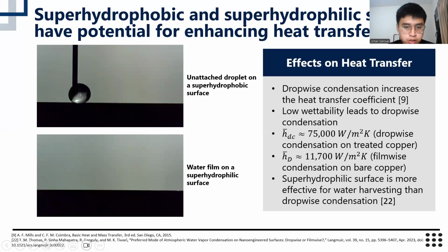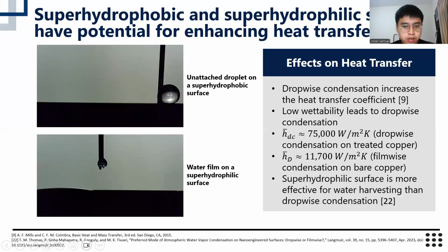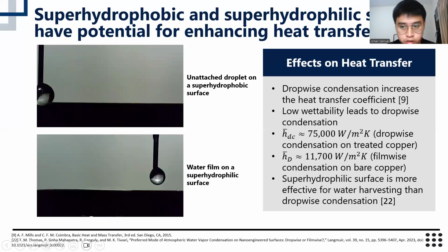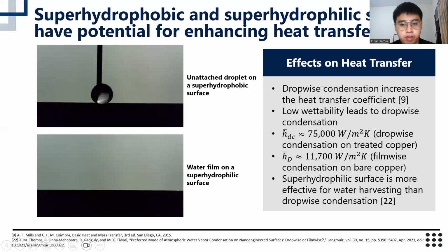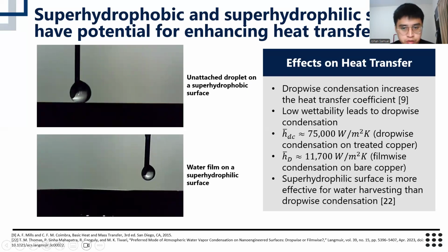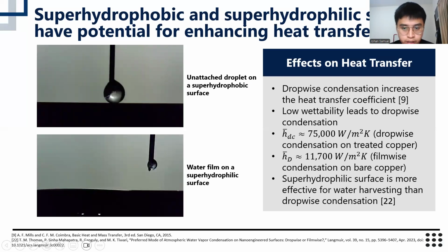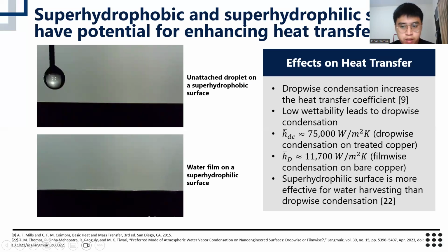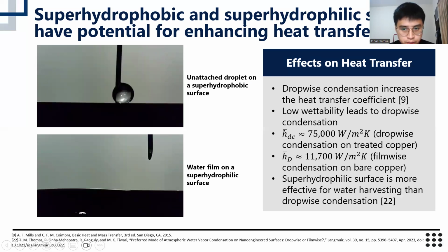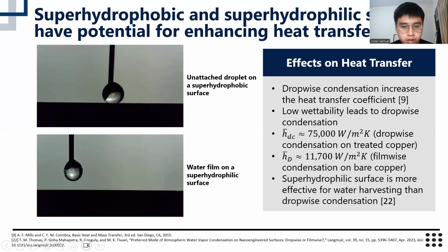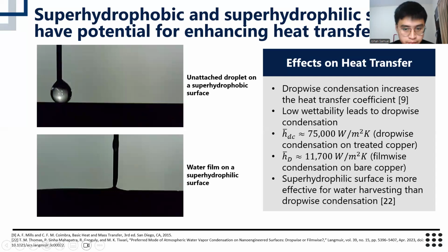So when a liquid is dropped on the superhydrophobic surface, the droplet will bounce and it will not stick to the surface. By having a superhydrophobic characteristic, the heat transfer from the steam to the outer tube surface is free from resistance, since there is no condensate hindering the heat transfer. Unlike hydrophilic, the film of condensate acts as a thermal insulation for the heat transfer to the tube surface. As we can see, the heat transfer coefficient for dropwise condensation is significantly larger than that of filmwise.